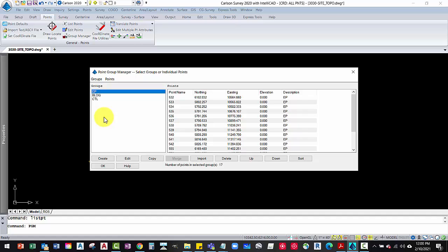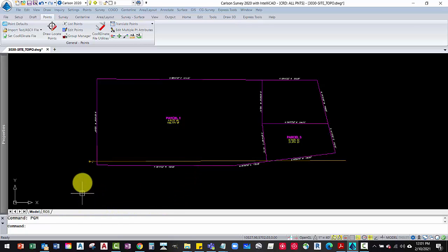standard that we do in our company, so I'll go through and make sure that the descriptions conform to our standard. Make a copy of the original, and then start working with that in Excel, and then save that out as a comma delimited file, that's a text file, but it's comma delimited. And you save it as that type of file, and then bring it in here. So I can see now things are pretty organized, and of course in this class I've got it so that I don't have to deal with a lot of that, but that's the idea here, is to get things sorted out the way you want. So now we've got these different point groups, and it's an easy way to keep track of it. So I'm going to click OK here. Now I know I've got a point group called building, or BLDG.